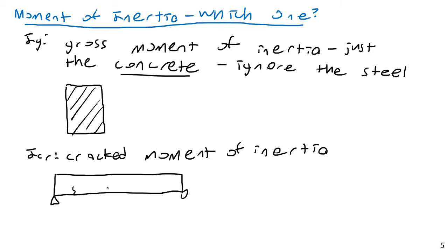And so there's going to be all these cracks along here, and this is perfectly fine because the steel is holding all the tension, not the concrete. But this portion of the concrete member down here is no longer even in contact with each other. This plane of concrete will no longer even be physically coupled to this plane of concrete here. This will be held together with the steel rather than the concrete.